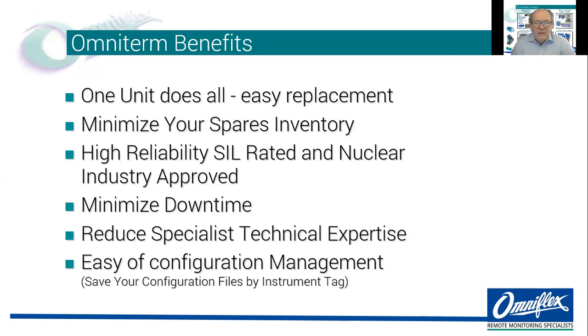You reduce specialist technical expertise as calibration is handled, linearization is all on board and standard, and it's a simple case of downloading a template file to the unit. Configuration management: template files can be stored on your local PC and managed by instrument tag number, and whatever plant system is in place for managing signal conditioners.